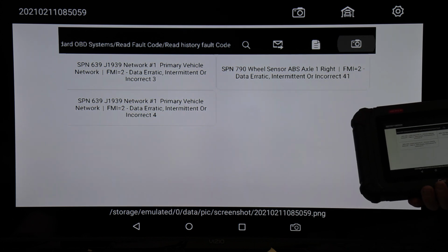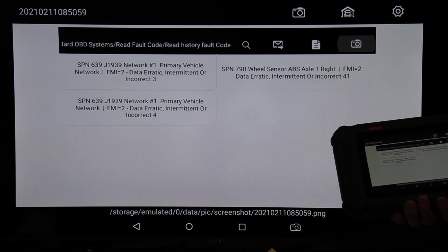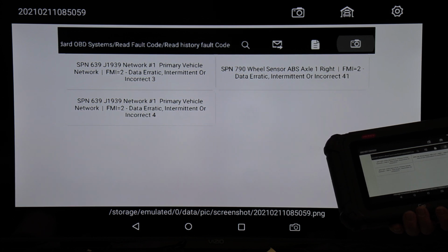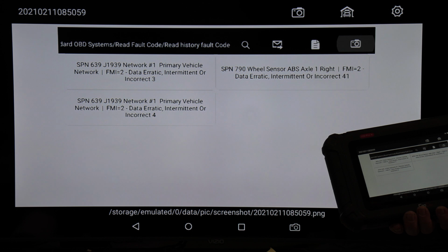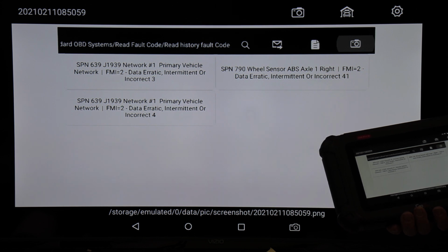Why I'm heading in this direction is that something happened back in the 1990s. ABS became mandatory in these vehicles. March 1st, 1997, tractors. March 1st, 1998, all straight trucks, trailers, and buses. March 1st, 1999, hydraulic brake vehicles 10,000 pounds or heavier.